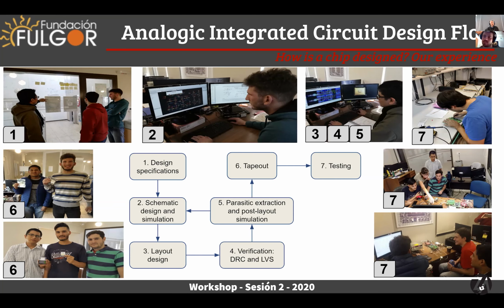And if we have an error, where maybe we don't match one specification, we have to come back to the schematic design and change something until we have the specification that we want in the parasitic extraction. Once all the simulations are okay, then our design is done and we move to the tape out. That's something that, in this case, Skywater will do, that they will manufacture the chip. And once we get the chip, we do some testing to see if everything is working correctly.